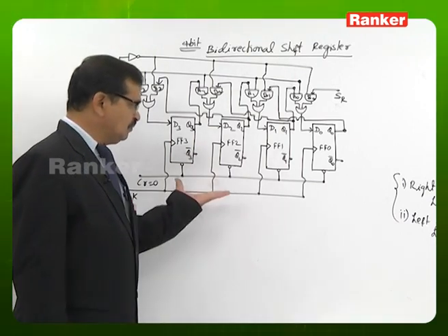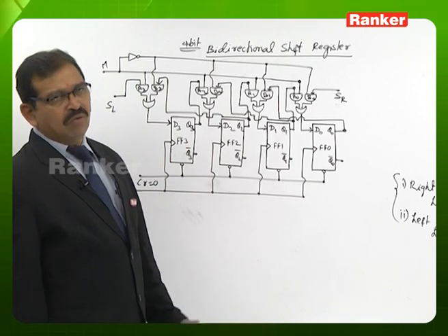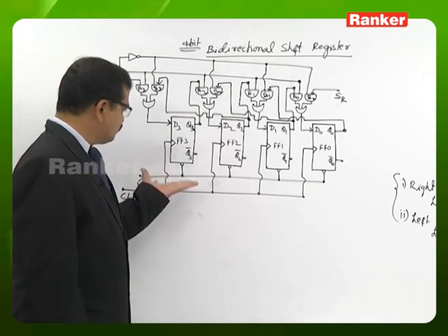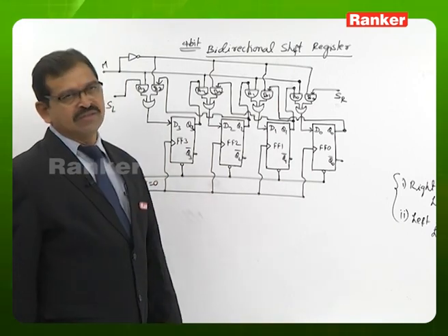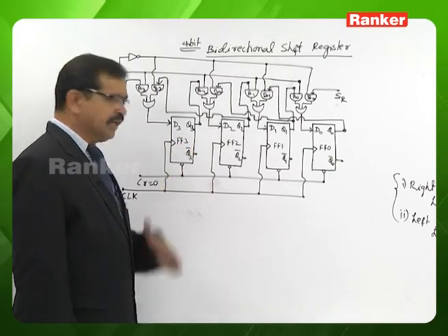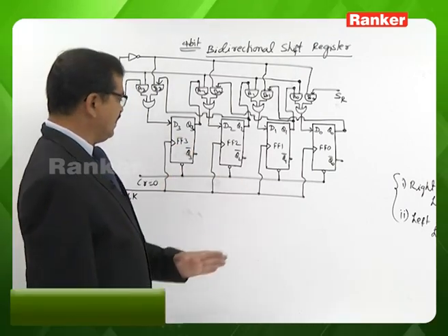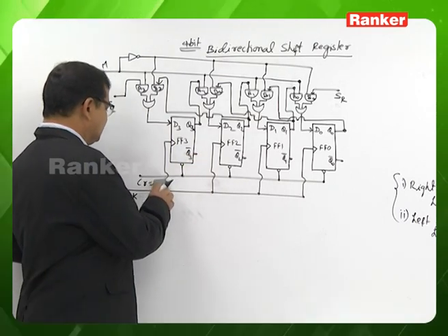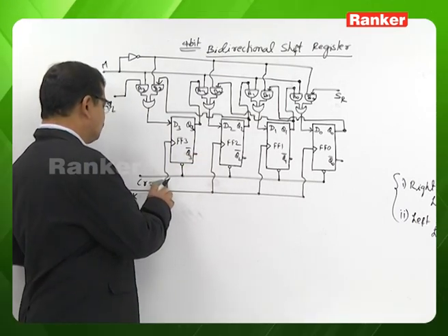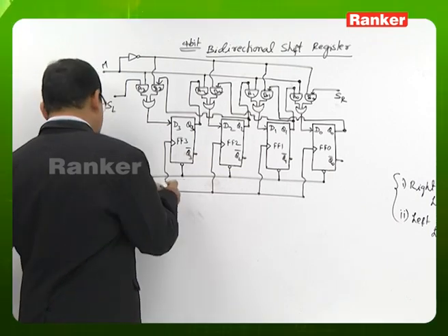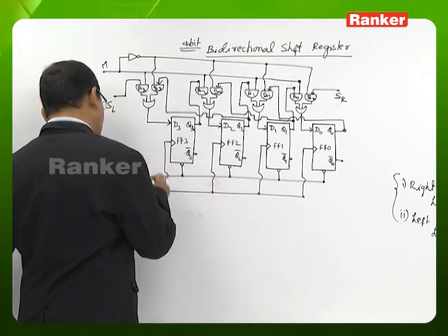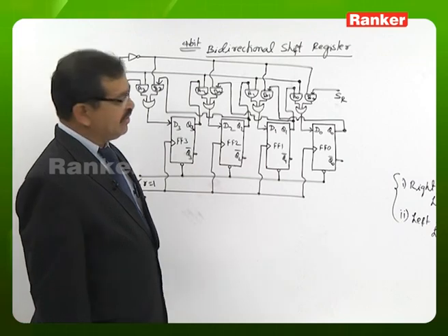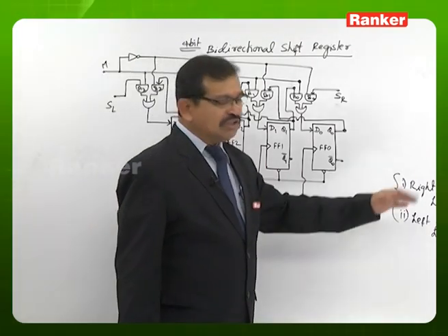But we know few of the flip-flops have only clear terminals, few may have only preset terminals, and few may have both clear and preset. It does not matter, but basically we first clear all the flip-flops. Let us consider here that these flip-flops have only clear terminals. After clearing all the flip-flops, the clear terminal is connected to 1. Later, for the right shift operation,